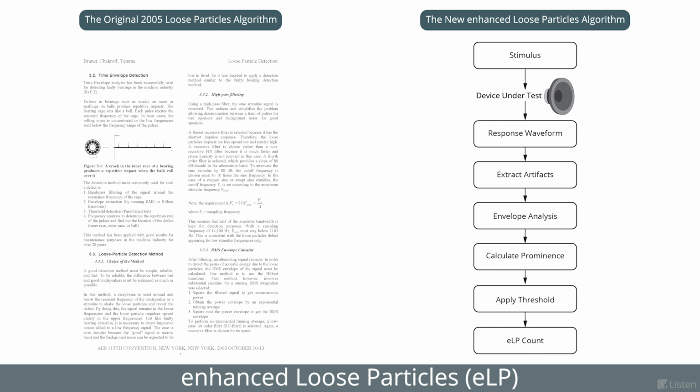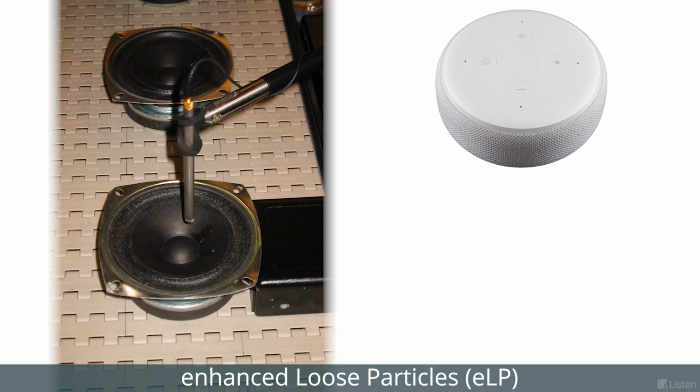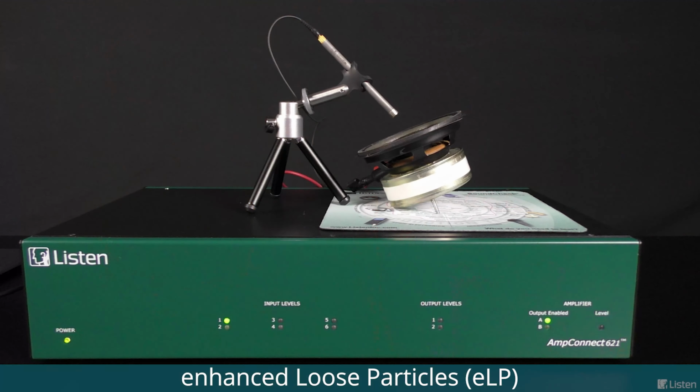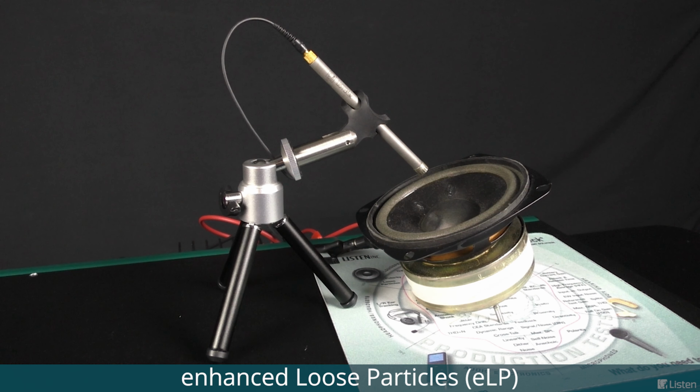In addition to identifying distortion caused by foreign material in the voice coil gap of the speaker, it is also valuable for detecting rattling parts on smart devices and Bluetooth speakers, and identifying buzz, squeak, and rattle in automotive applications. Let's look at how our new enhanced loose particle algorithm analyzes a good speaker and a speaker with transient distortion.